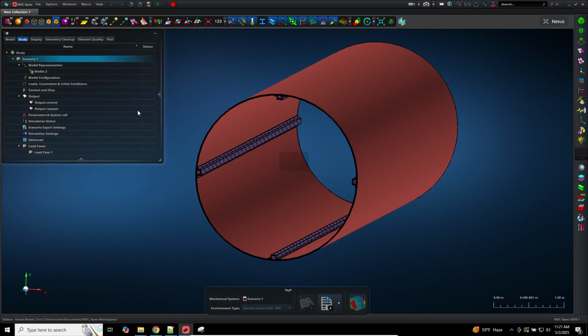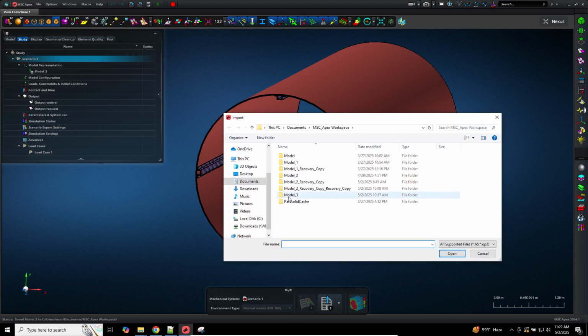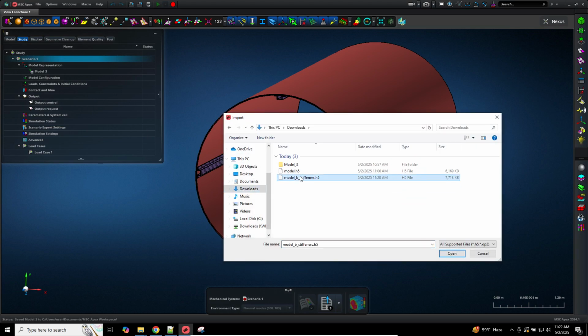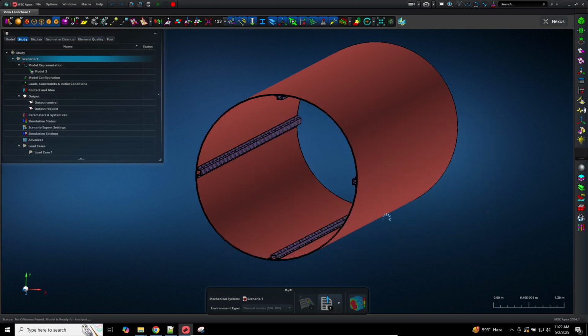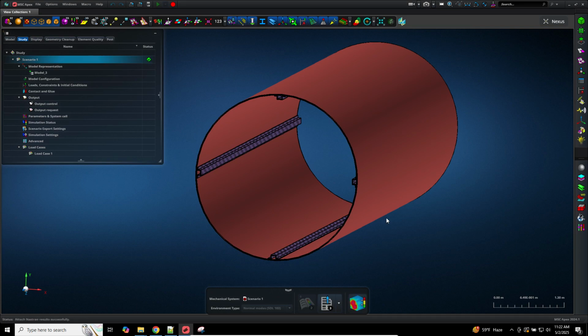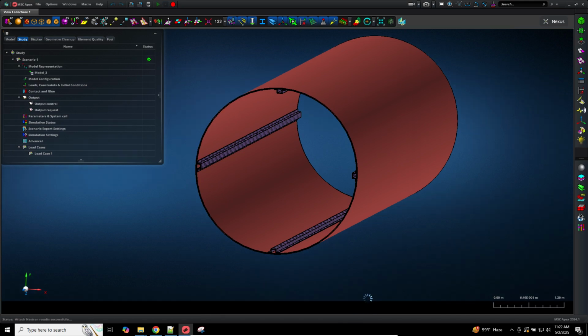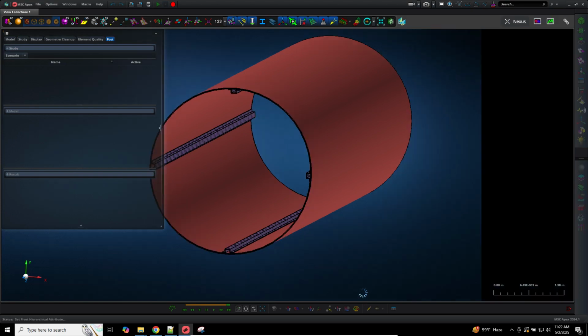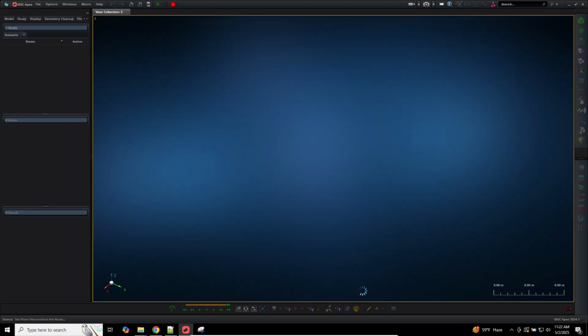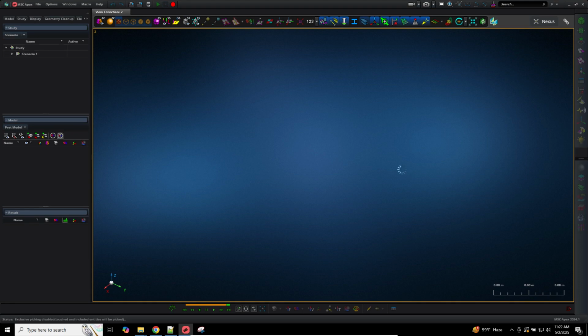So let's do this. Right click on the scenario, attach Nastran results, click on browse, go to that directory where you have the H5 file. This contains your eigenvectors. If you're performing a statics analysis, it will contain your stresses, your applied stresses, your strains, and your displacements. Here at the bottom left, it tells me attach Nastran results successfully. Here in this bottom horizontal bar, click on the color cube. This goes into post-processor mode. And we're going to look at some of the natural frequencies.